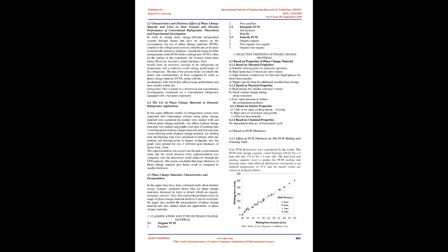Moreover, the influences of some parameters such as PCM thickness and phase change temperature of PCM on the performance of refrigeration systems are reviewed. The advantages and drawbacks of using PCM in the evaporator, condenser, compartment section, and compressor are evaluated. Using PCM at the evaporator section minimizes the fluctuation of compartment temperature and provides stable conditions against thermal load variations. Since incorporation of PCM at the evaporator increases the compressor running time initially and raises the condensation temperature, several investigations were performed to incorporate PCM at the condenser section. With an alarming rate of rise in the use of refrigerators, along with their total electrical consumption in today's world, the application of PCM on refrigerators looks like a viable measure to increase efficiency and reduce energy consumption.